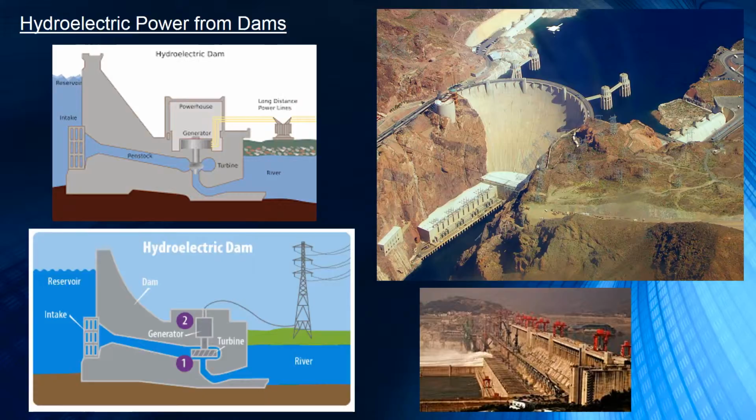They're also very expensive to design, build, and manufacture. Systems also won't work efficiently if the water source has dried up or if there's not a lot of water flowing through the dam, for example due to dry winters or summers. If the tide is not very strong, the turbine won't turn as fast, so the magnets won't induce a high voltage or current. So you won't get a lot of power out of that, which is not great.